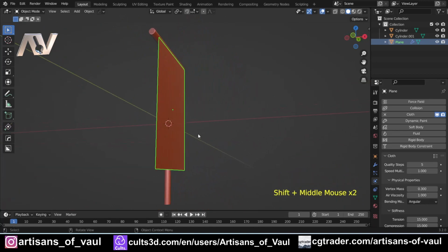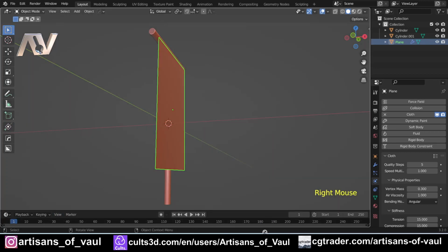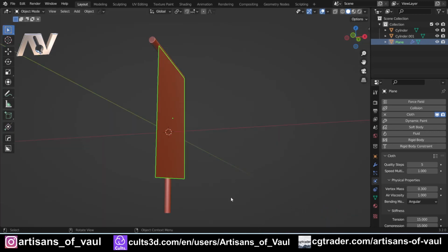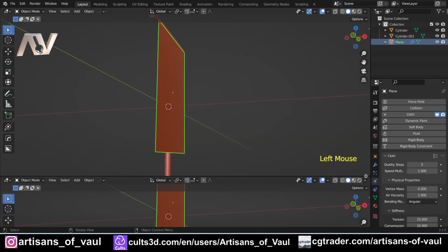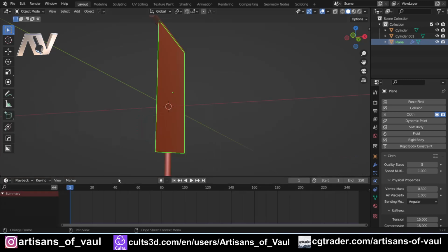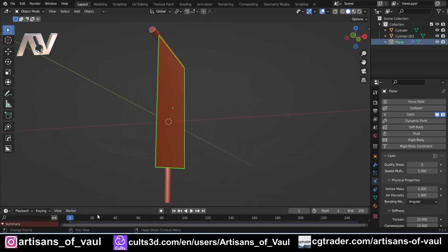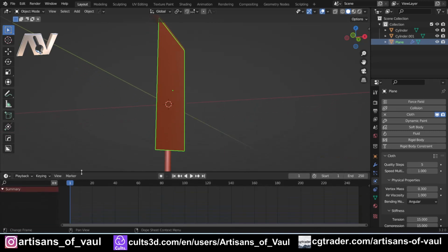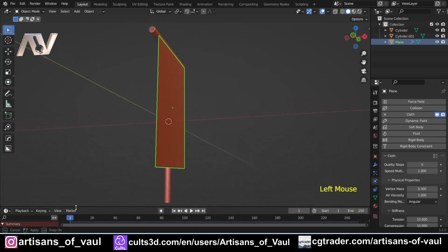First thing we do to set this going is we use this at the bottom, which is our playback timeline. If you don't have this, it might be that at some point you've got rid of it, so it looks like this. To bring that up, all you need to do is take your mouse, go to a corner, so for example here or here, not just the bottom, it's got to be a corner where you will find your mouse changes to a crosshair. Click and pull up and you'll get another viewport tab, and all you do is come up here, go to timeline, and it changes it to this timeline, and we don't need that much space. We just need to see where the marker is, and this is what you'd normally do for creating animations if that's what you're interested in. I'm going to bring that down.